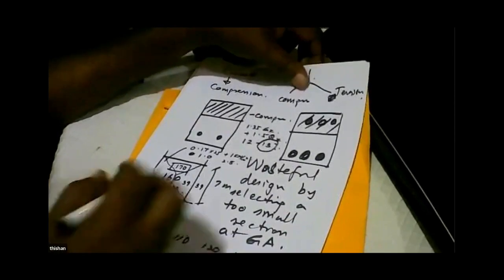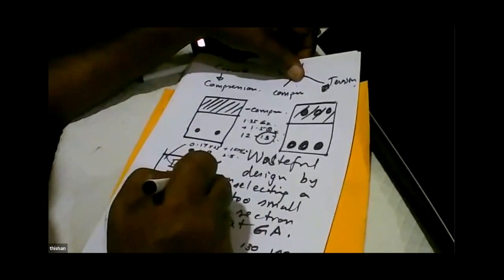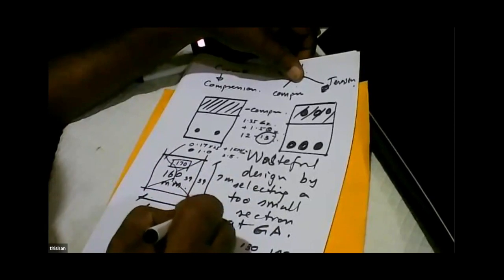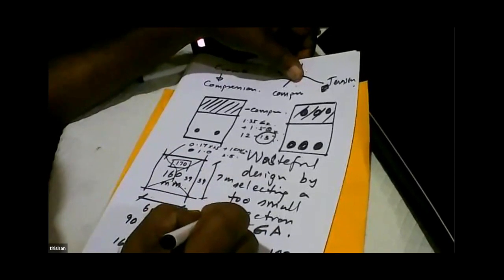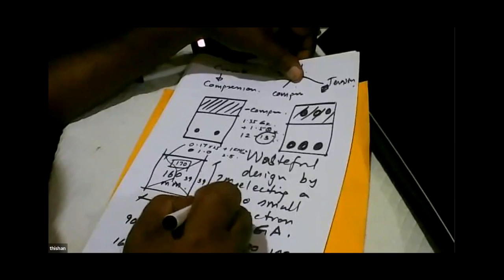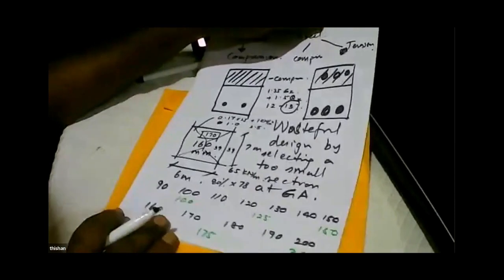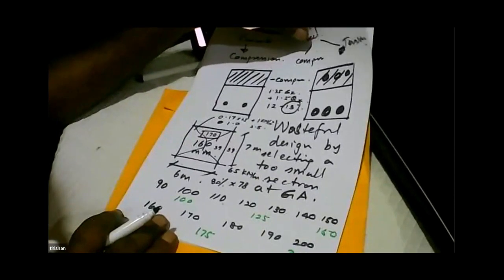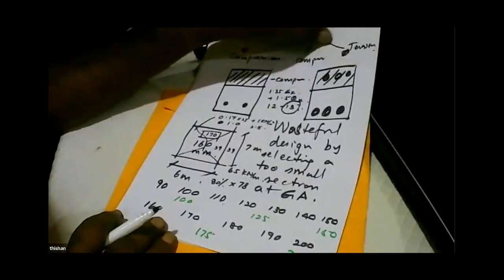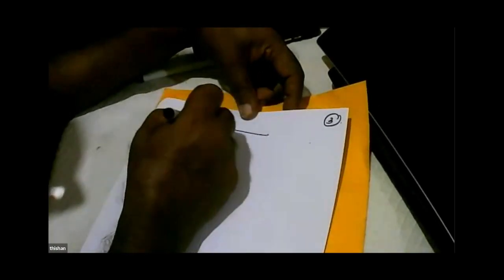So if it is 13, 39 will come from this side, 39 will come from this side, but because it's trapezoidal, I'll say 80% of 78 will come. So the load will be about 65 kilonewtons per meter. So with some simple calculation, you can straight away decide what is the load that is going to come onto this beam. So it is 65 kilonewtons per meter. This is page number 2. Then you will say, okay, page number 3, 65 is going to be a continuous beam.